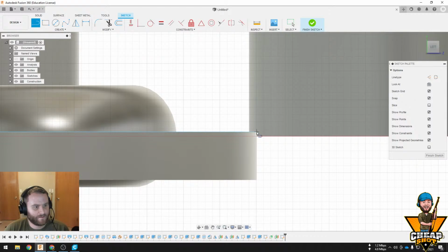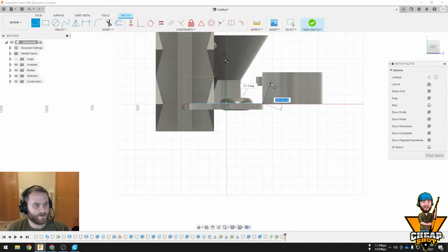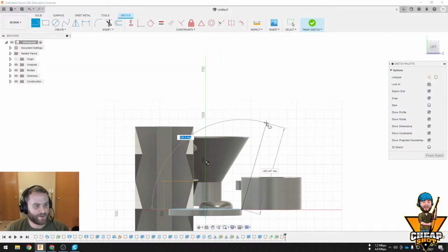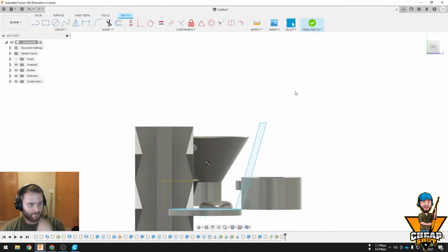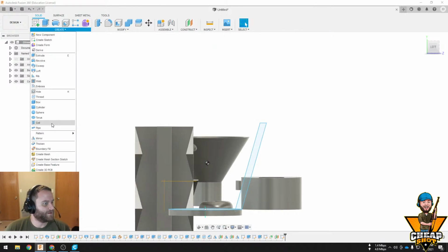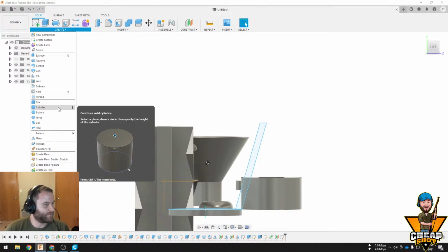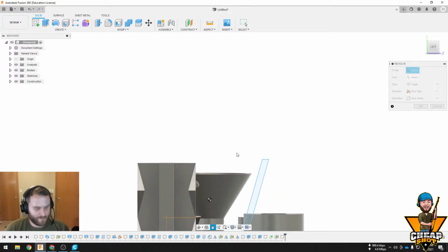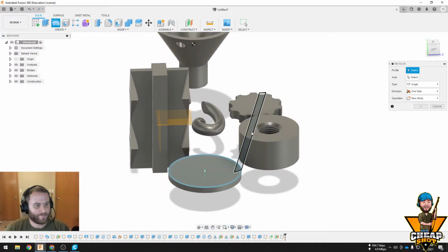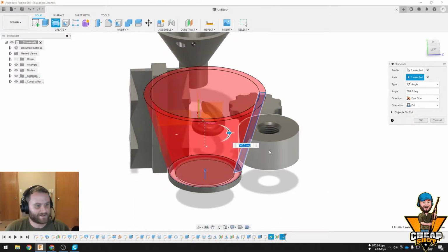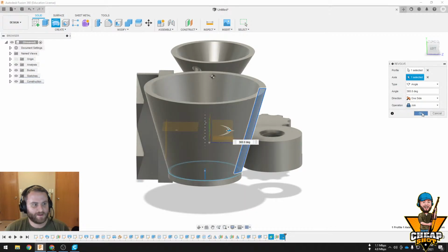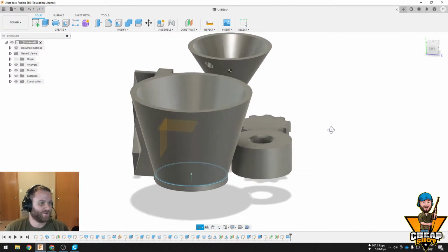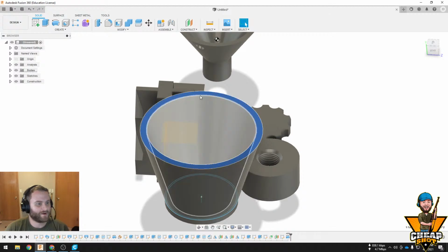Let's say we come up. If you're just tuning in, we're making a cup. I can come into the thing, it doesn't matter. And now what am I looking for? Not pattern, what am I looking for? I'm looking for Revolve. That can be my profile. That can be my axis. Ah, boom. I don't want to cut, I want to join. Boom, that's my cup. That's a horrible cup. That looked worse than what we did before.